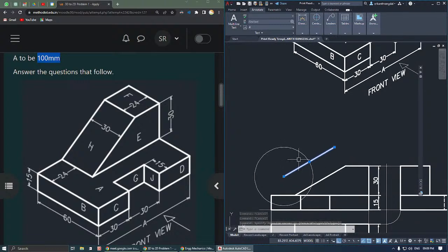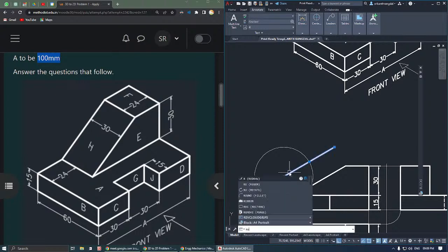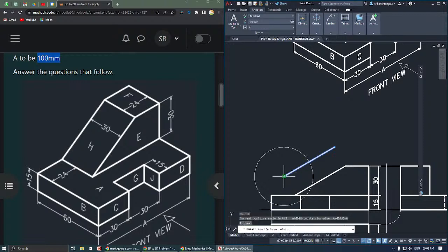So for drawing perpendicular, there are two ways. One simple way which we have discussed in the class is use rotate command. Select the object, give rotate command, then select a point, and after selecting a point, you can see I'm getting the rotation. Fine. So if I just click at this point, the same line will be moved to the next position. But I want a copy of this, so click on the option copy, and now click here. So when I click a copy, then an extra copy will be created at 90 degrees. Fine, because ortho option was on, it has directly taken the line at 90 degrees.